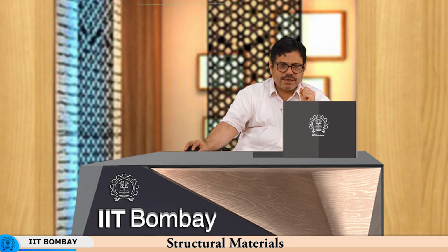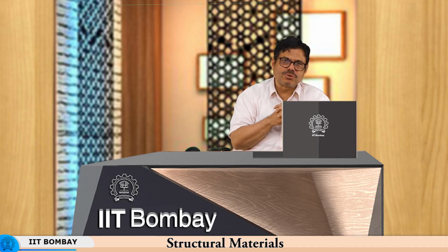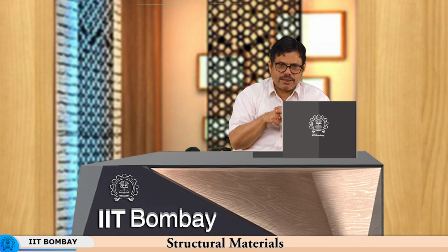The other aspect is, you can have localized decarburization. Many times the water vapor or the presence of oxygen itself, dissolved oxygen, results in reaction of surface carbon with oxygen, causing local decarburization at the surface.